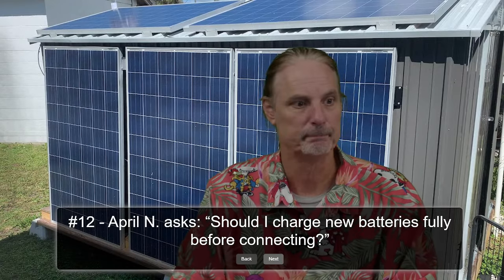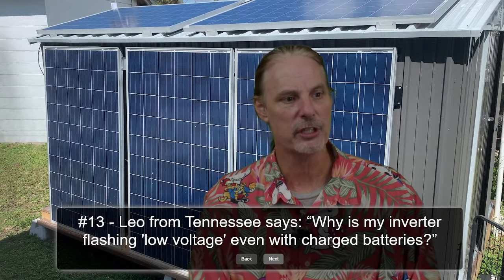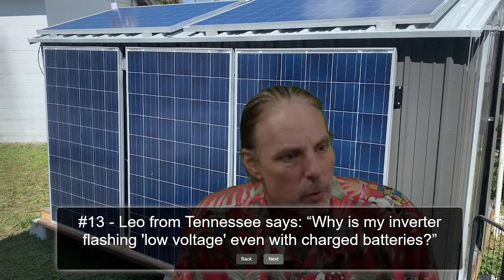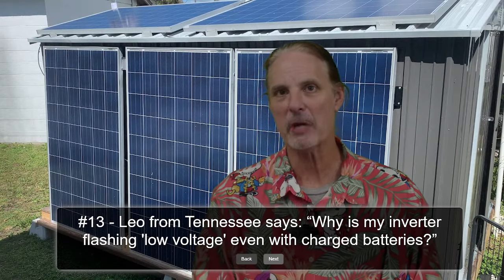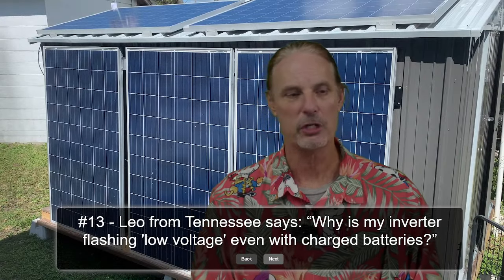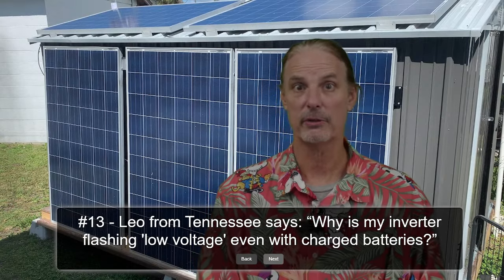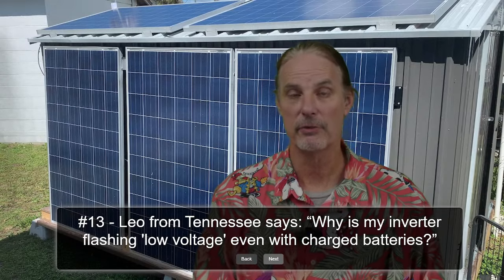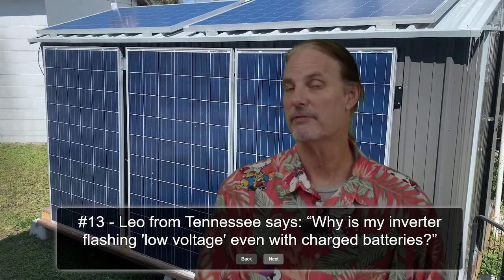Leo from Tennessee asks, why is my inverter flashing low voltage even with charged batteries? And as we start to see the theme pop out here, the question, Leo, is how do you know the batteries are charged? Or are you looking at a BMS state of charge that says, hey, you've got 15% of your batteries available? Or are you looking at a state of charge that says you have 100%, but yet you've never run it down